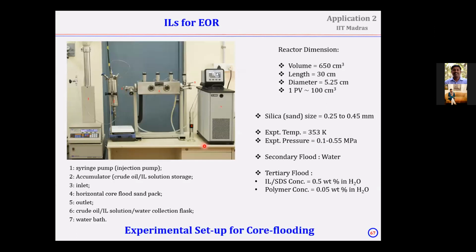We all know that the natural flooding, that is primary flooding, comes naturally. After that, researchers do secondary flooding through steam or hot water at the designated places to push the crude oil out from other designated places. And after secondary flooding also, research says that more than 25 or even up to 27 or 30% of the crude oil is still there underground. And it is very, very important to take it out. And that's what we wanted to mimic in the tertiary flooding.